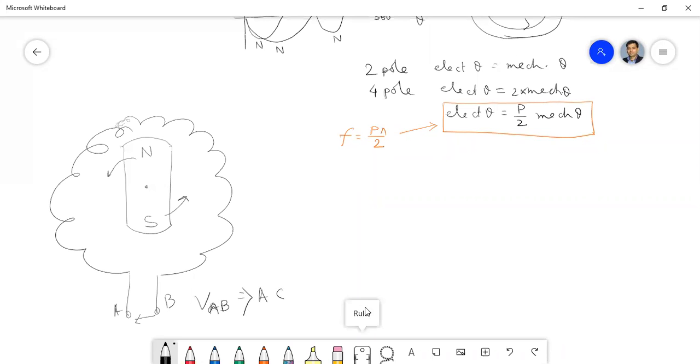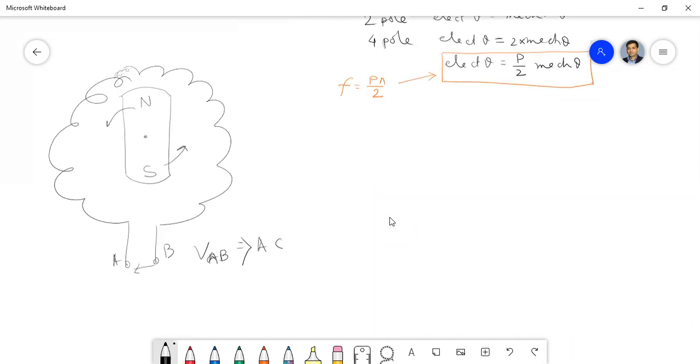Are you getting? Yes. And suppose I want to make a different DC machine, not the DC machine in our book. This is how another arrangement we can make a DC machine. It's very simple. If we have a magnet and we rotate it, and I have a coil like this in the stator, it's very easy to have an alternating voltage, because again I am telling the same thing: DC voltage cannot be induced. Only AC voltage can be induced or developed.